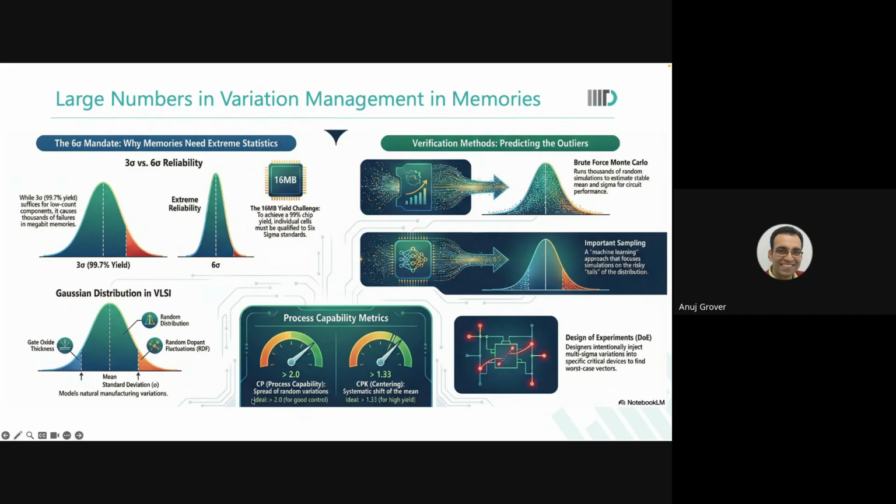In leakage, the relationship becomes exponential. At other places, the relationship is a complex mix of linear and square, or there are secondary terms, second order and third order effects which start to come in. As a memory designer, what do you consider as inputs for, say, self-time design? Memory cell current and leakage are inputs for you.